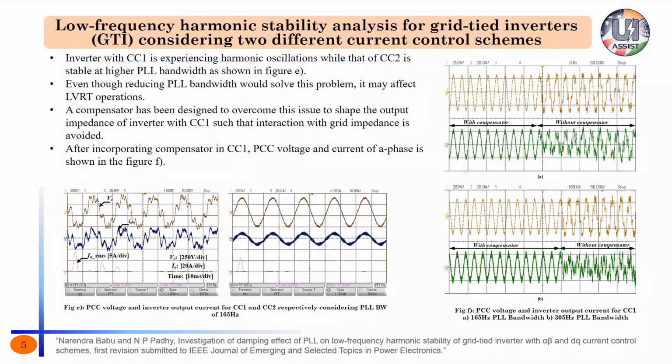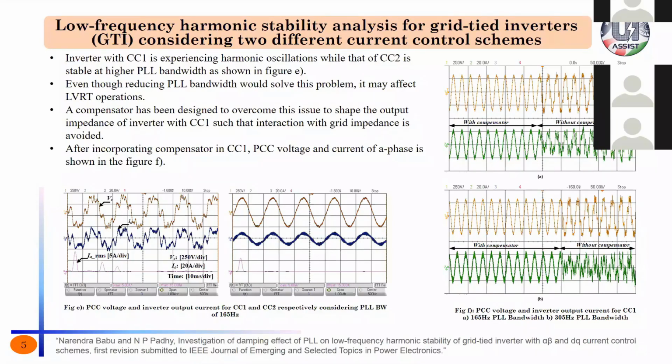So to overcome that, we thought of going for a software solution where we can design or develop a compensator which can nullify or counteract the impact that the PLL is creating, and shape the impedance such that there is no negative damping region. So that we could achieve, and we could test it with the hardware as well.